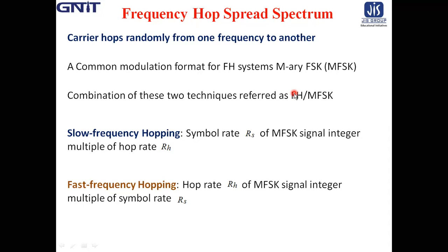However, the capabilities of physical devices used to generate the PN spread spectrum signals impose a practical limit on the attainable processing gain. It may turn out that the processing gain so attained is still not large enough to overcome the effects of some jammers. So, what are the alternative methods?